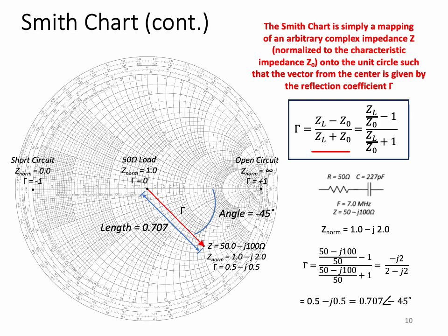If the load impedance, on the other hand, had a negative real component, negative resistance, as for example an oscillator might have, then gamma would lie somewhere outside the unit circle. So the Smith chart was usable not only for stable systems, but also for unstable or oscillatory systems.